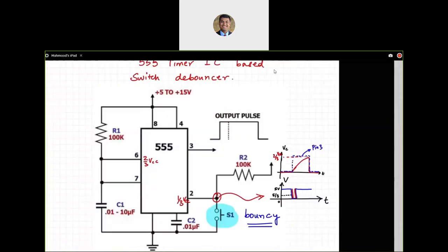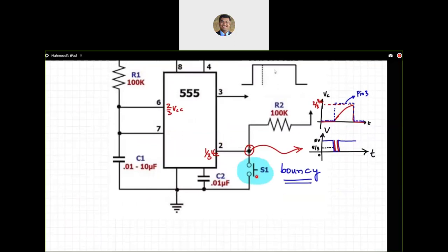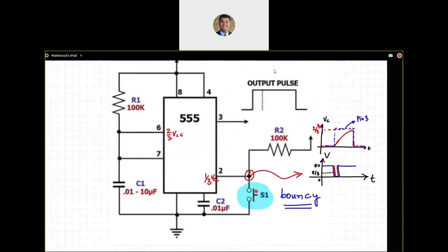Well, if you see this diagram, all I would do is I would remove the bouncy switch from here, S1, and at pin 2, I would connect the 5 voltage sources, and the other side of those 5 voltage sources is connected to ground. I would not put this resistor 10K, so it is not present. This R2 is not to be included in capture Pspice.